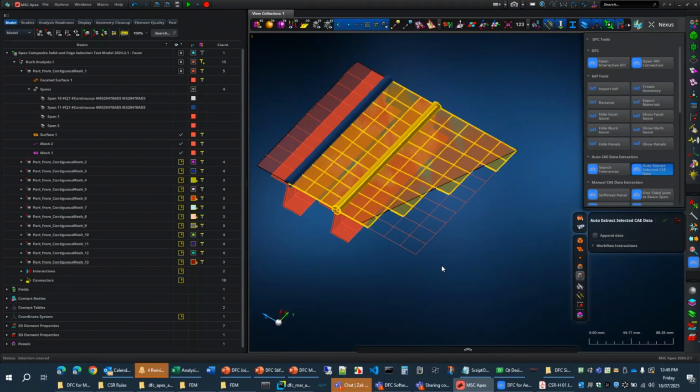The code will then convert it to SI, do the calculation in SI, and then the output is whatever the input unit was, whether it's SI or imperial, it will export it in the input unit. Okay, that explains it. So you are using the buckling curves in SI units, not imperial. So you have all of the setup in SI units originally. Correct. I take any imperial data, I convert to SI, and that is then used in the code. Okay, that explains. Thank you.